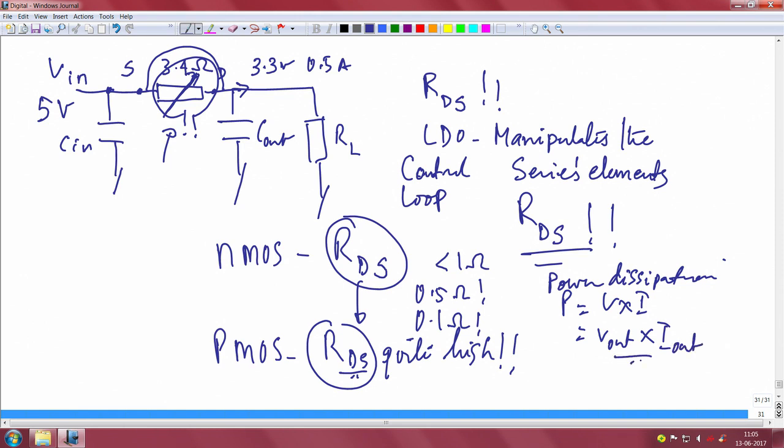You can do this, and input power is also important, but it is quite simple, it is nothing but V in times the I in current, and what is important is the power dissipation of the LDO. This is very important. This is nothing but V in minus V out times I out, output current, nothing but the drain current as we called it.